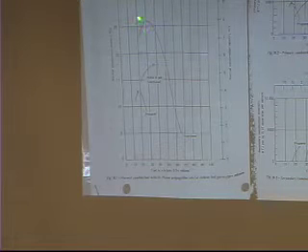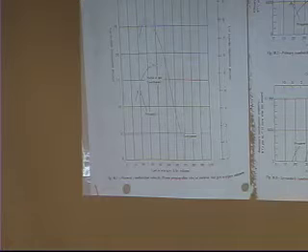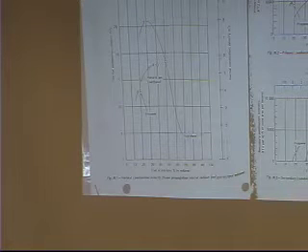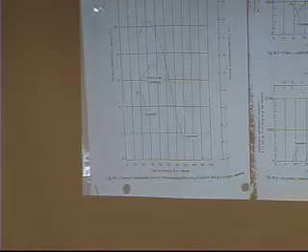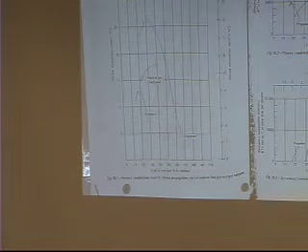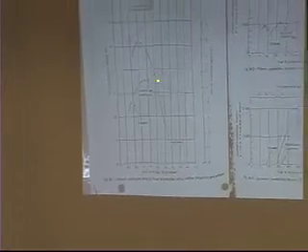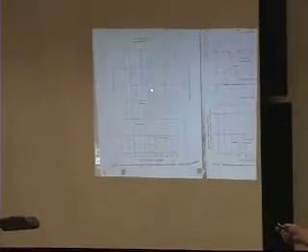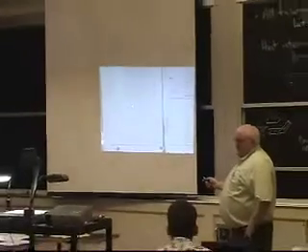Stoichiometric is where theoretically you have just the right ratio, number of moles of oxygen to number of moles of fuel to burn it completely. So stoichiometric mixture is perfect ratio of gas to oxygen. The neutral mixture is where you essentially get, in a sense, a practical flame that's neutral. In most cases, there's not a big difference. In acetylene, there is a difference.